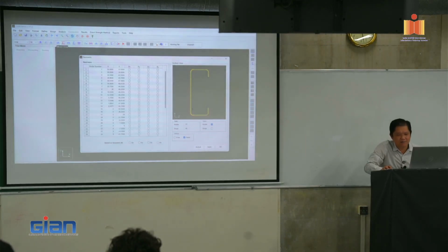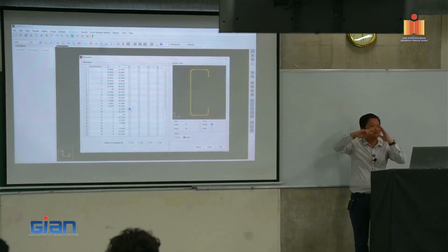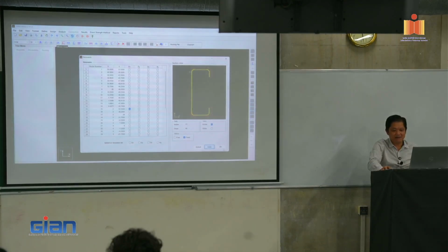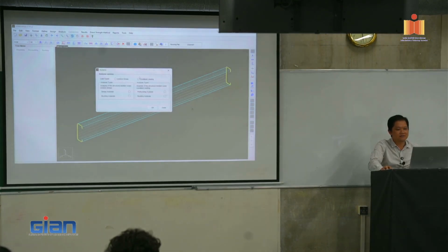Let's say I want to put that restraint about X at node 15 here. I click on here. Like you have a rod, the bar, right? So you hold that one and you see how it works. Apply, okay, run it. Then you run the analysis, and you can see how it works.